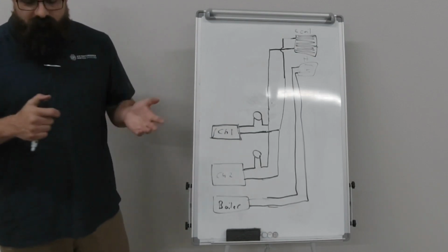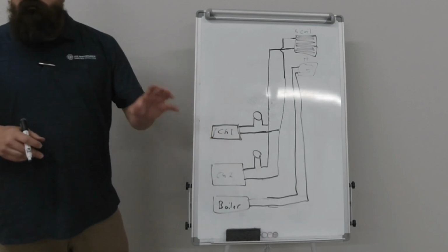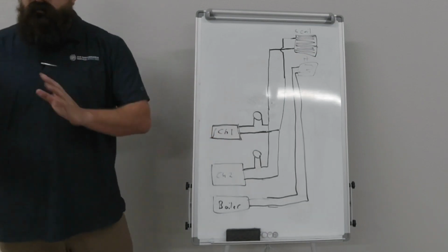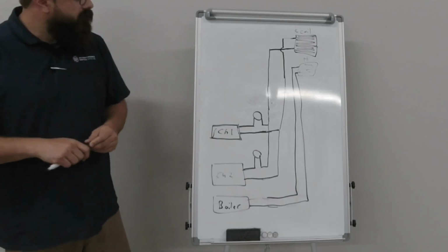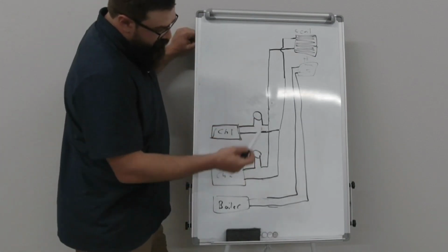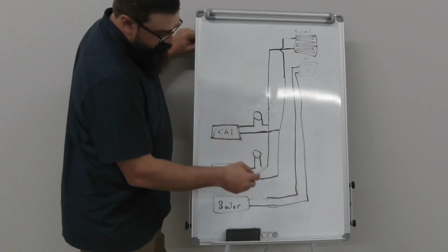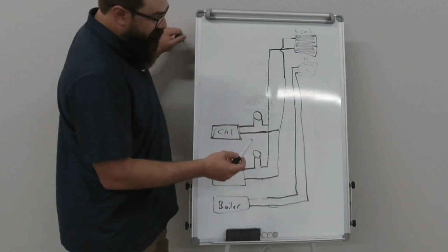So if you have multiple pumps, dedicated would be that pump is only for that chiller. Common is the pumps can do either chiller or both chillers, depending on how the system's set up for flow. So this is a basic dedicated setup. You would have some kind of valve still, or backflow preventer, something to prevent pushing through the other chiller.